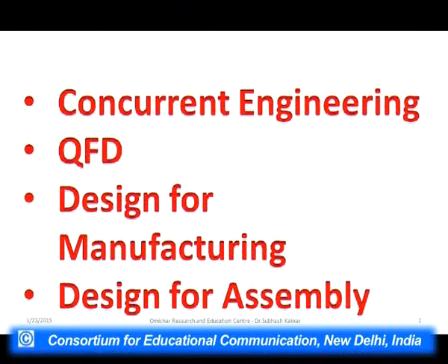Today's topics will be concurrent engineering, QFD, design for manufacturing and design for assembly. Concurrent engineering, doing everything simultaneously. Whatever is required in design of the product, all the functions required in designing the product work together simultaneously, parallelly, and the time of launching a new product is saved.